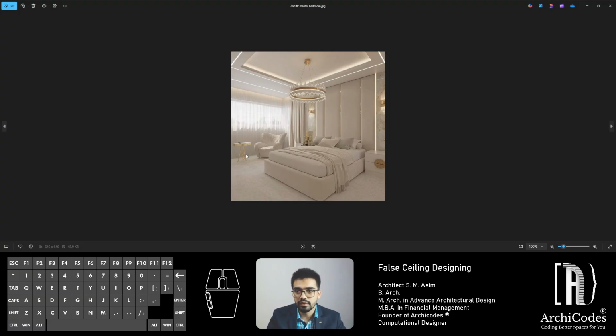Let's go to the master bedroom. Now this is also a very long room with 2 fans, and I'm mentioning 2 fans specifically because that changes the false ceiling design. For example, in this room, which is a square room, this false ceiling design works. But in that case, I need to be a bit more creative, change this design a bit to fit into a longitudinal room, which is twice the size of this room, but not in magnitude, just in one direction.